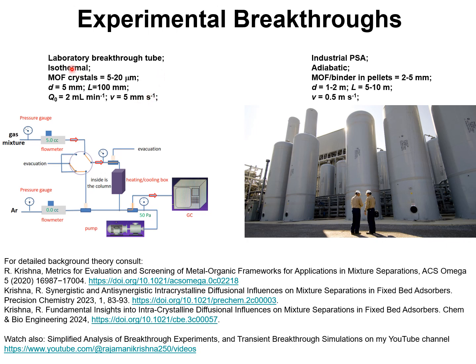Such experiments are almost invariably conducted under isothermal conditions in fixed bed tubes of internal diameter 5 millimeters or so, and the length of the packed tube is approximately 100 millimeters. The MOF crystals packed in the tube are usually about 5 to 10 micrometers in diameter.